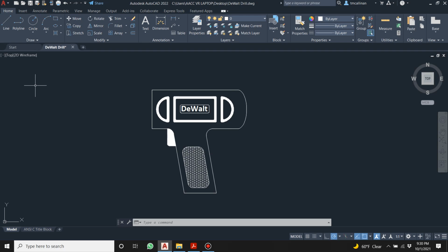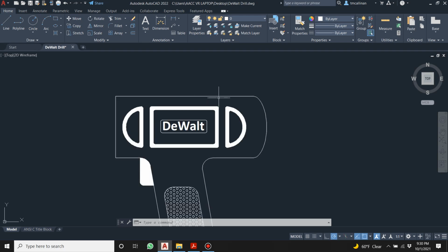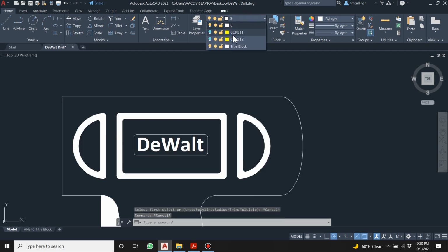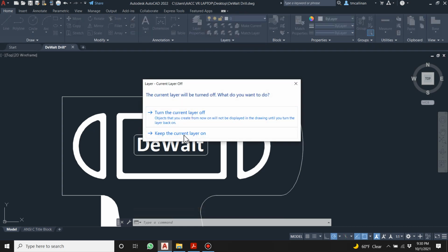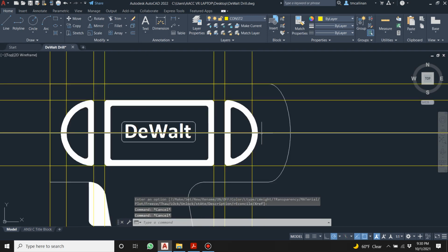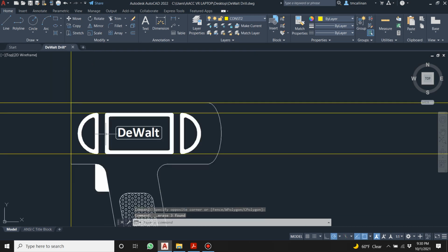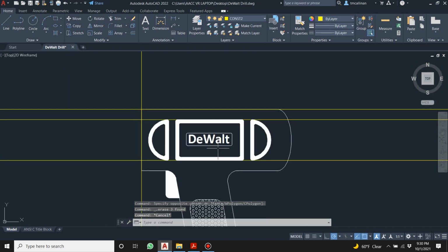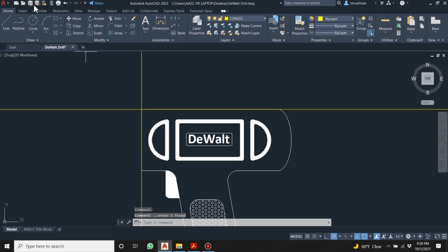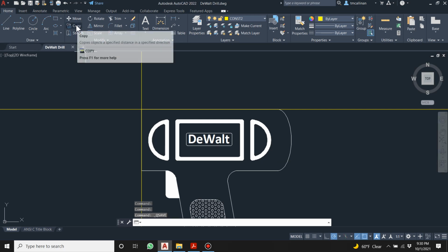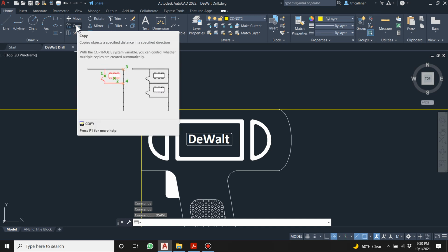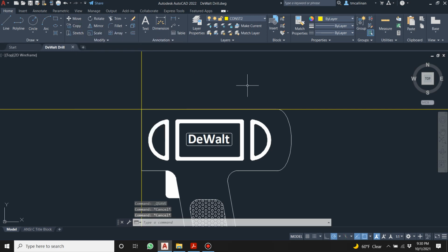And then I designed this about 15 years ago. It's not bad. Let's turn on the old yellow things, the construction line, and I'm just going to get rid of some of these lines. We don't need them all, like so. And we're on to, let's save it. We're on to step number 3. It says typically the sections of both sides of a drill are held together with socket head screws. So let's put them in.